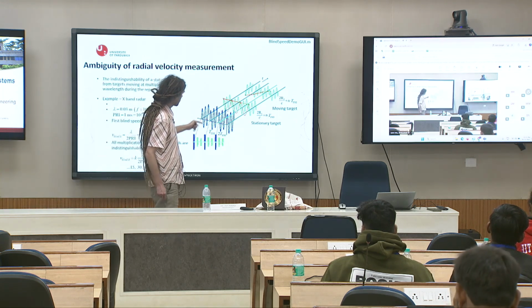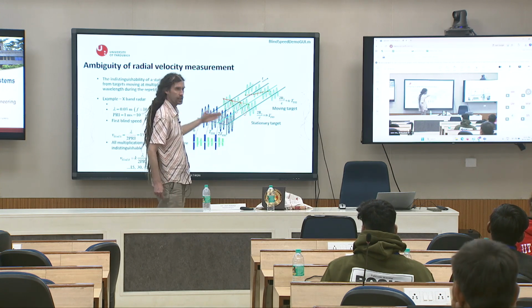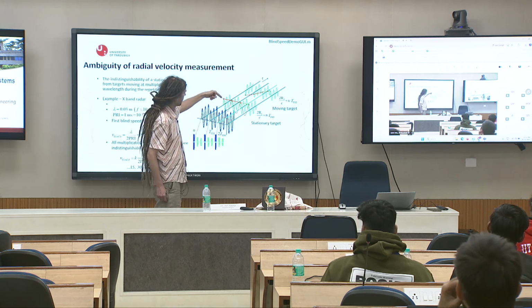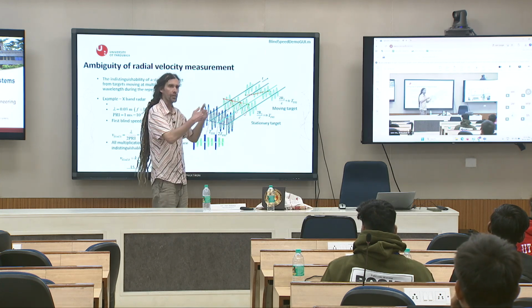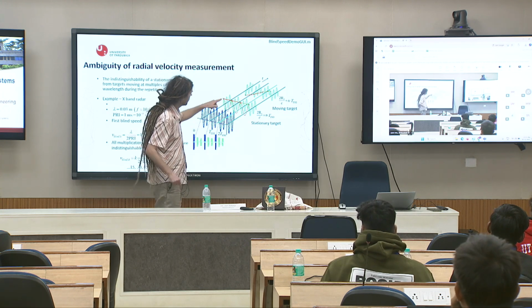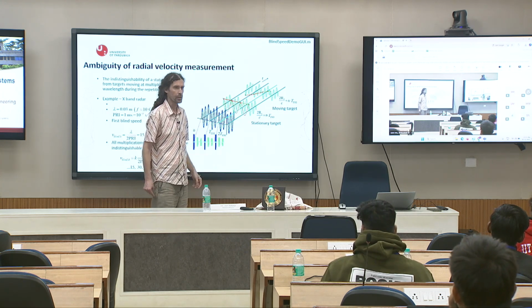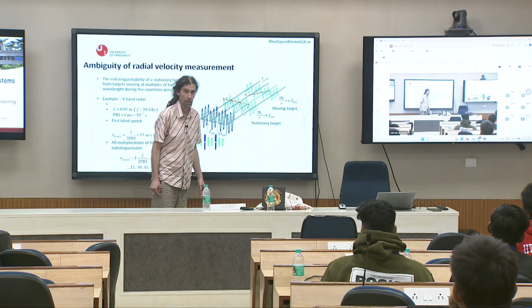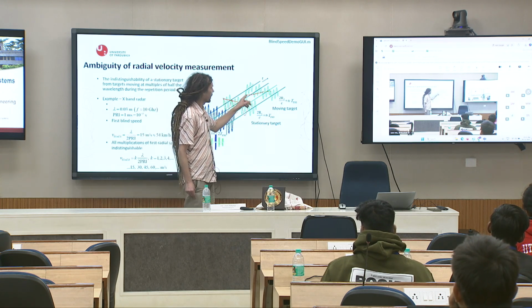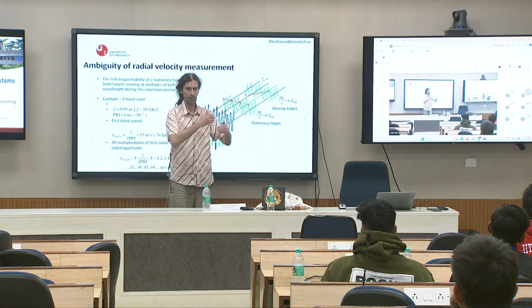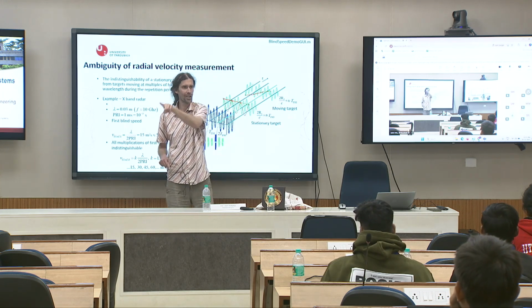Look, it is a 1 µs signal, 1 µs pulse, and so on. These are different pulses, and these are the moving target responses. If the target is shifted by half of the wavelength, I will get this result. This is always the same, so it means it doesn't move. But if not, it will be a different value, you can see that it changes.